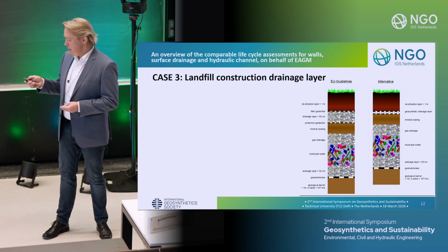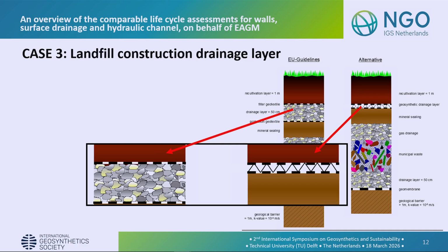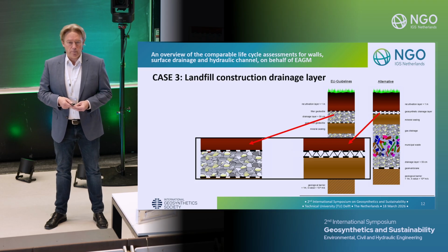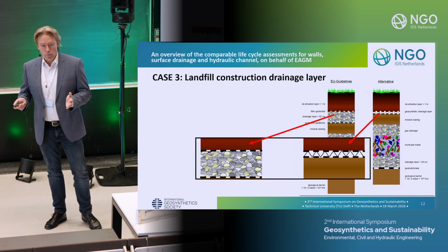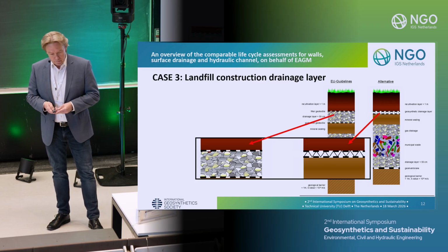And you can see here on the slide the main difference, that's the thickness. What we compared in this case is really only the drainage layer itself. So that means we compare only the LCA impacts of the drainage material as well as the drainage core, because all the rest of the construction is the same. I have a filter above, I have a protection layer below, so we can really focus only on the main things which are different.